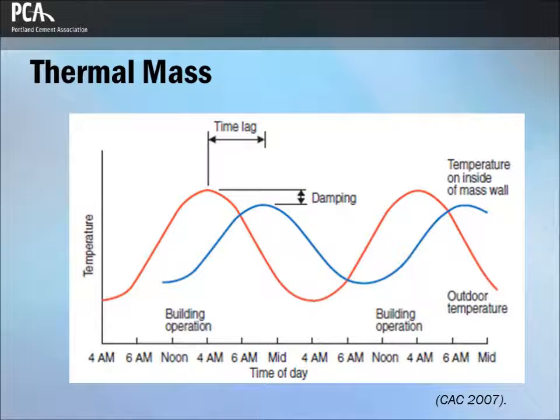One of the key aspects of thermal mass is it can shift the energy demand to off-peak time periods, as shown in this plot. For example, a building could be heated up during the daytime hours and then contain that residual heat in the cooler nighttime hours.